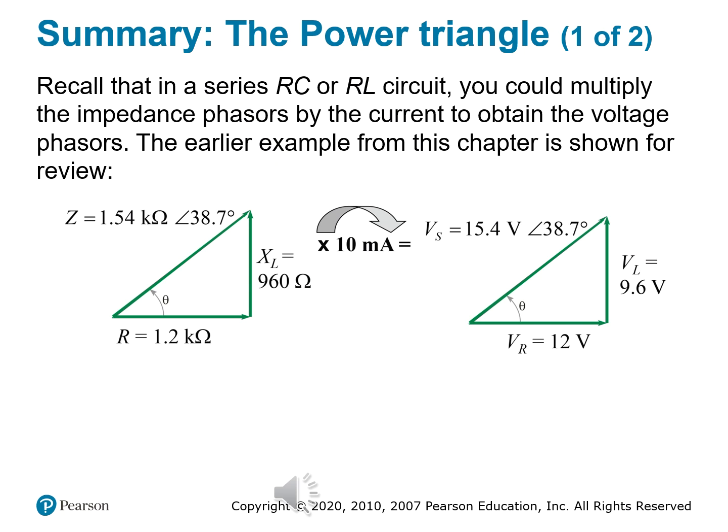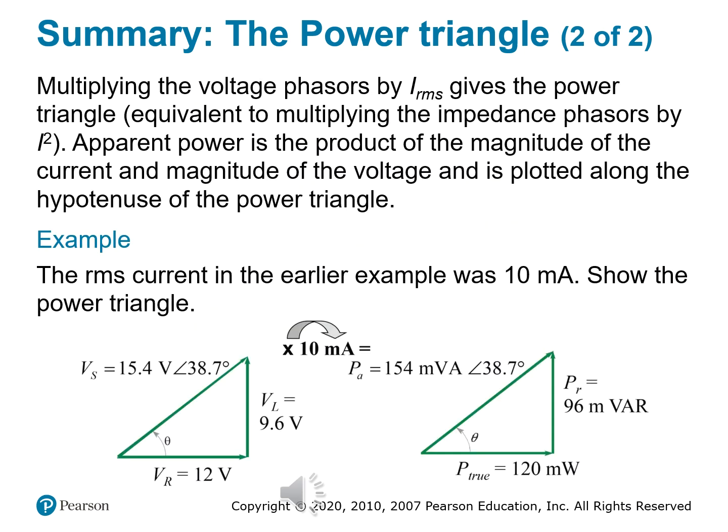And this is where electrical design becomes energy aware, right? You know how much power is actually used with P, how much is stored and returned with Q, and what your circuit looks like to the power source, S. So it all starts with impedance, leads to voltage phasors, and then ends in the power triangle. Power triangle complete: watts, VARs, and VA, volt-amps.